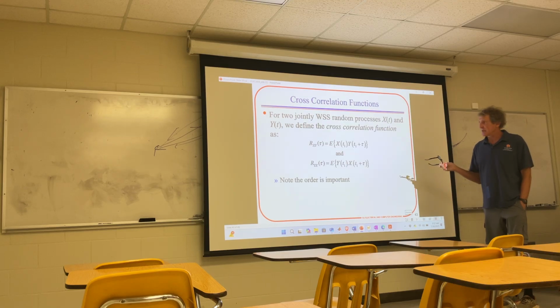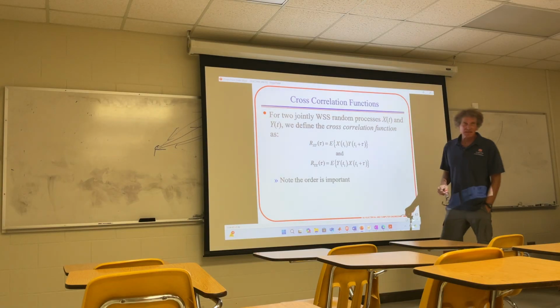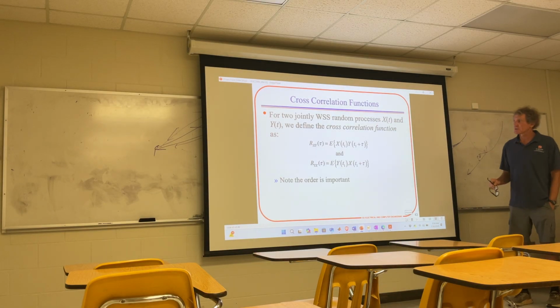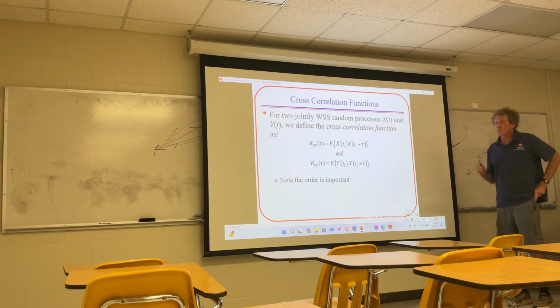Now, an estimate here, really, if it's a capital R, not a script R, that's in the statistical domain, assuming you would have an f of x and an f of y, but you don't usually have that. So it's almost always done in the time domain. Do you all remember with ergodic, the time domain autocorrelation function would have the same value as the statistical autocorrelation. It's called ergodic. Wide sense stationary signals don't have to be ergodic, but for all intents and purposes, we assume that.